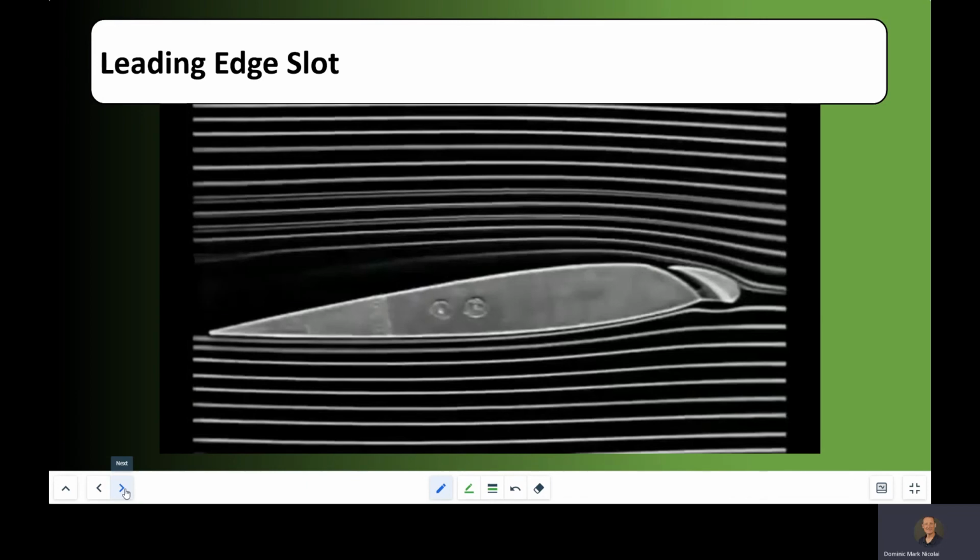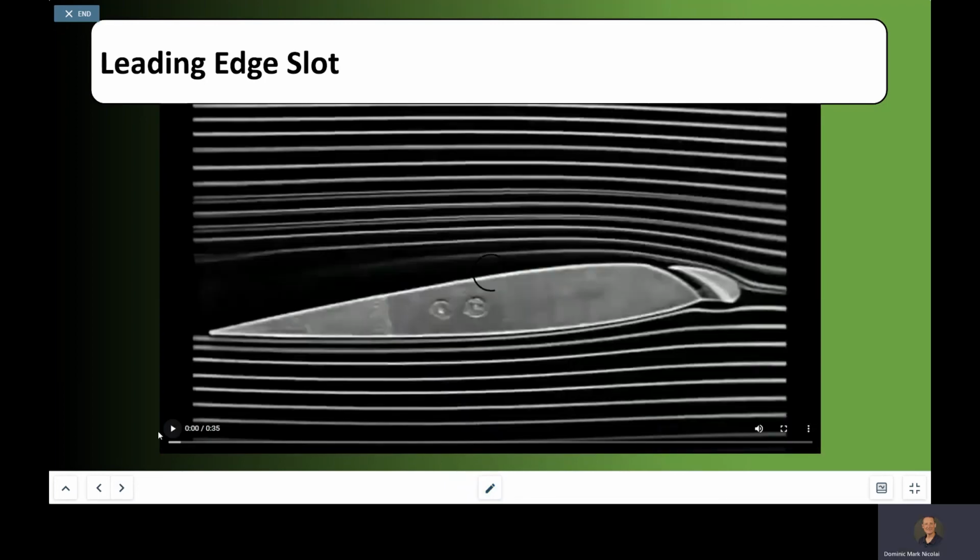As you get into your bigger aircraft, those aircraft have a critical wing on them, and that wing is critical in that it's at a certain speed to develop enough lift for flight. Obviously, during takeoff and landing, those wings on those airliners are not producing enough lift by themselves. Too slow is what's happening. So they augment that. Of course, flaps help augment it. But here's another one, a leading edge slot. You can see that slot has opened here at the leading edge of the wing.